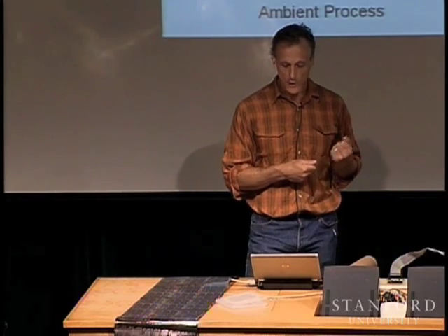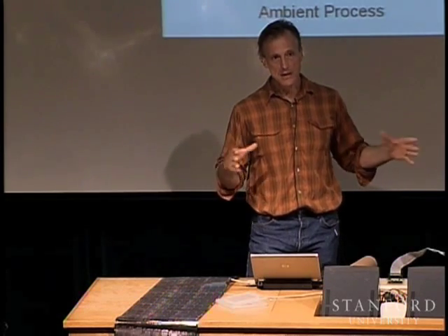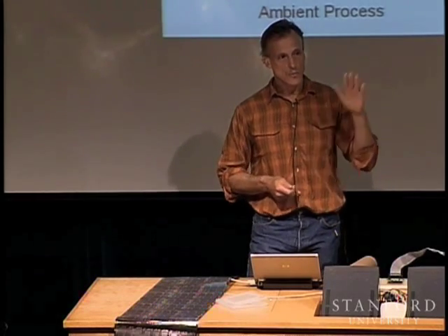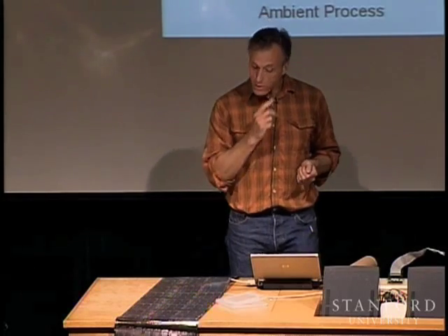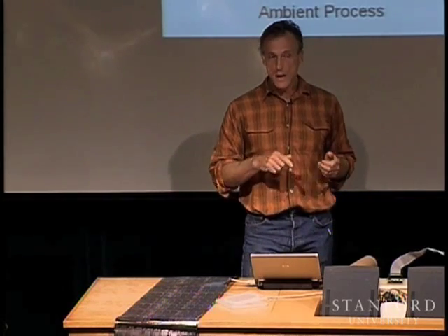Another neat thing about having the plastic stored that way, wrapped up tightly like a roll of toilet paper, is that it protects itself from particulate contamination. When we're dealing with big pieces of glass, or with silicon wafers for that matter, we do it in a clean room because we're exposed. Every time we move this surface around, it's vulnerable to particulate contamination. Because the web rolls itself up, it's protecting itself from that.